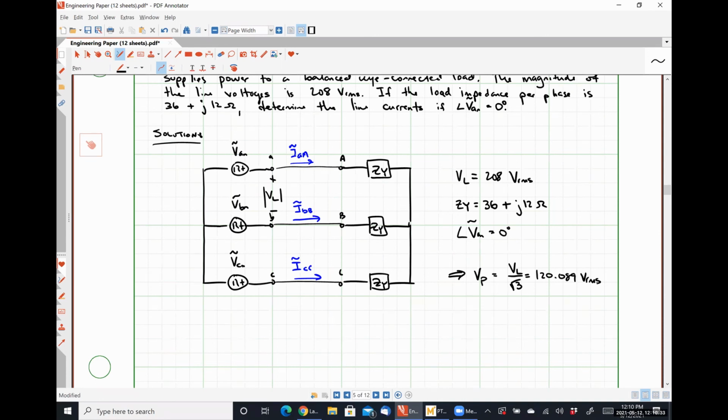So that would be considered a multi-phase system, but it isn't necessarily a 3-phase system because it's really just one phase being split into 2 identical phases. So there's no difference in the phase angles. Well, the difference in the phase angle is, if it's 0 on one, it's 180 degrees on the other. So it's not 120 degrees out of phase. If that makes sense. Or if I potentially just confuse the hell out of you. But that's how your home distribution works.